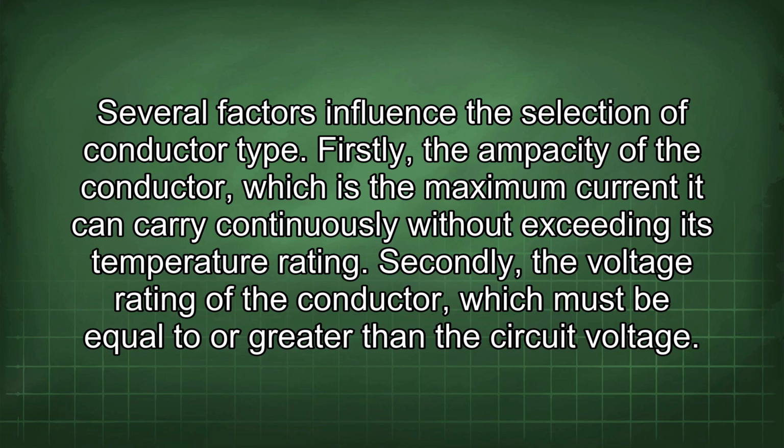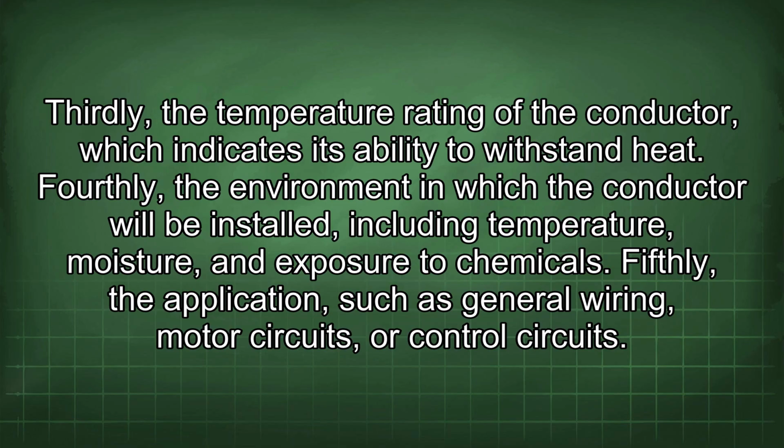Firstly, the ampacity of the conductor, which is the maximum current it can carry continuously without exceeding its temperature rating. Secondly, the voltage rating of the conductor, which must be equal to or greater than the circuit voltage. Thirdly, the temperature rating of the conductor, which indicates its ability to withstand heat. Fourthly, the environment in which the conductor will be installed, including temperature, moisture, and exposure to chemicals. Fifthly, the application, such as general wiring, motor circuits, or control circuits.